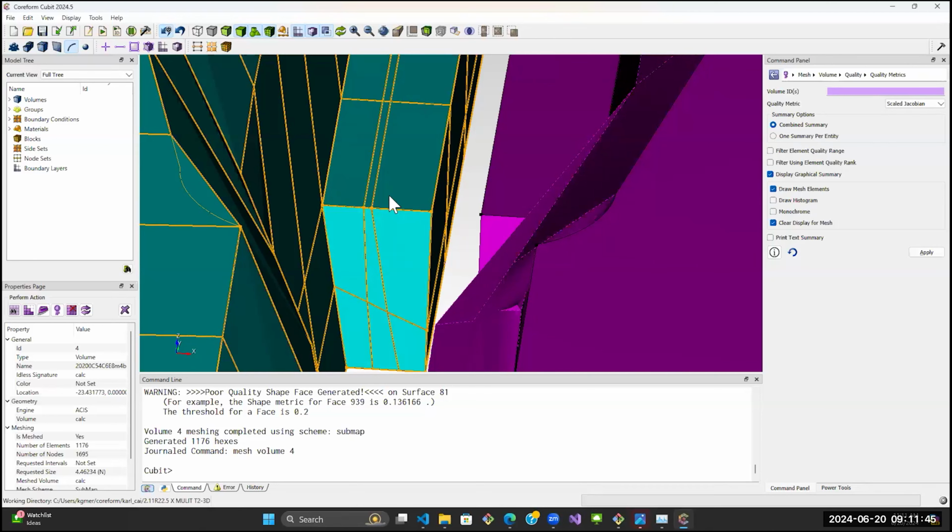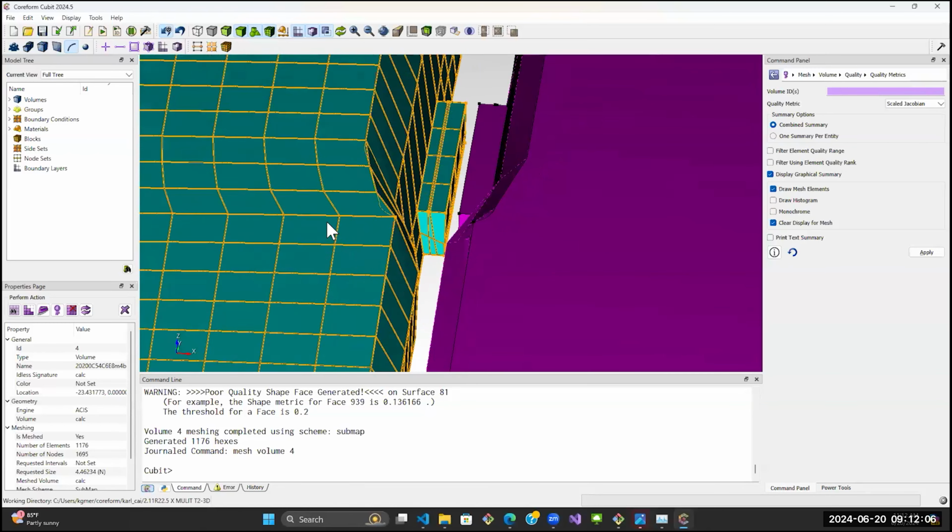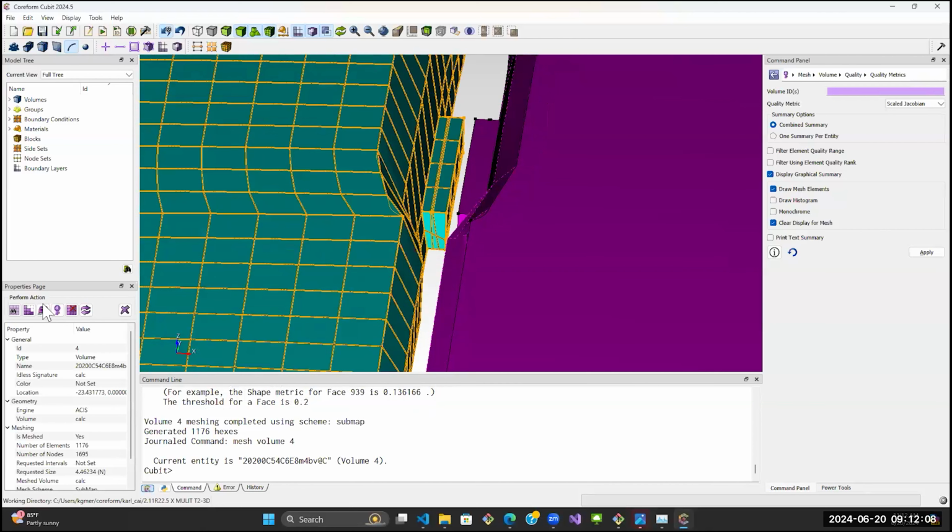Compositing these curves together is one way to help control our element quality. Cubit wants to acknowledge that vertices may have some value. You may need to attach something at a vertex. So the mesh is there at those vertices by default.